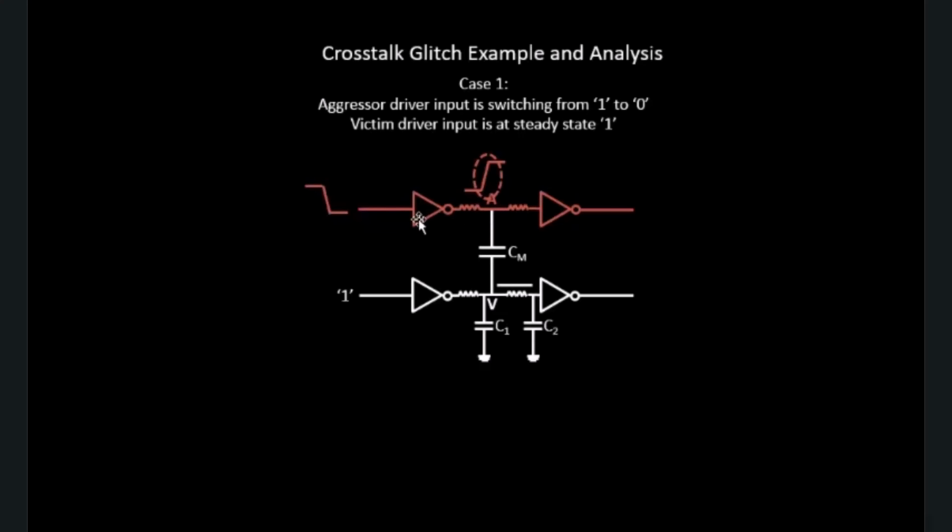So whenever this particular tap is open, it tries to charge all the capacitances. It tries to put water in all the other capacitances which are grounded, and it also tries to put water in this leaky bucket as well. Since this bucket leaks, whenever there is a charging behavior at the output of the aggressor, this water leaks and gets deposited in this particular bucket.